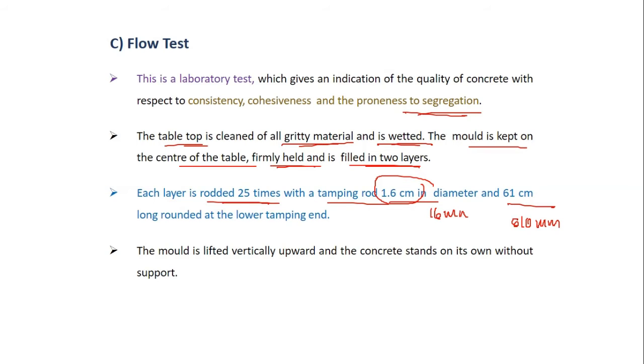Okay, so what we are going to do is fill this mold with concrete completely, and then the mold is lifted vertically upward.